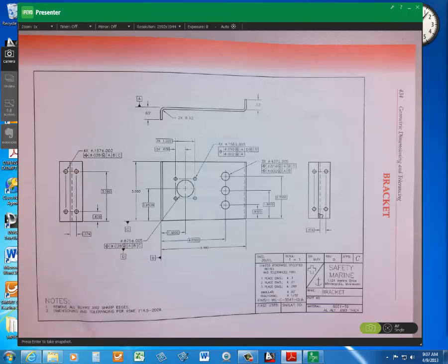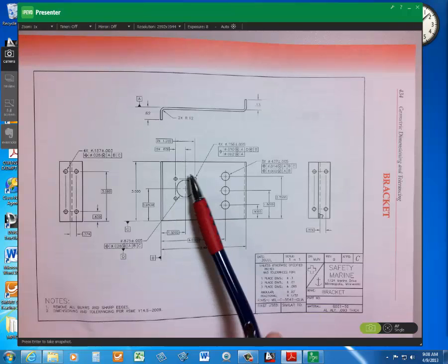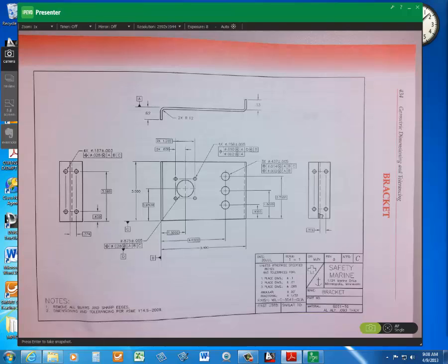for each hole. All right, so it's a single composite pattern. Each position is to be considered singly. All right, the 0.156 diameter, which is the 4 small holes around the large hole. How many of these features are there? There's 4. Location dimensions is rectangular coordinate.